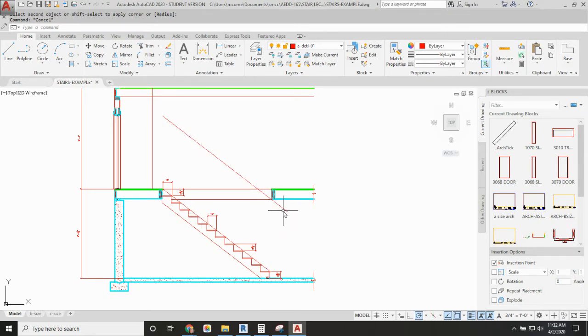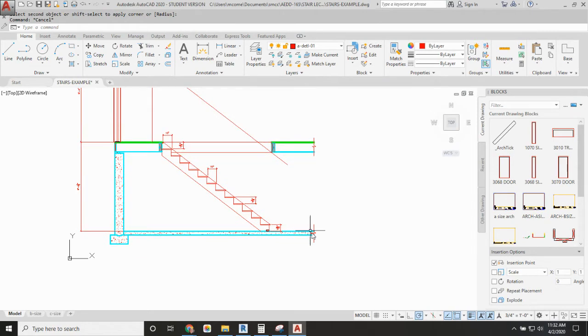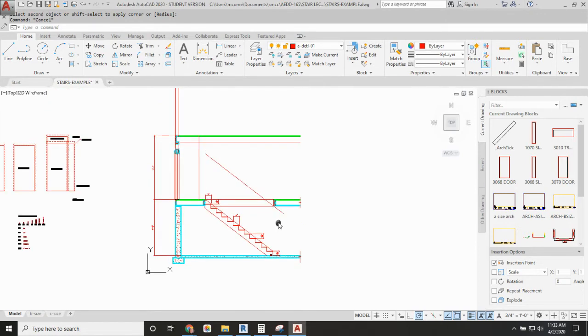And this headroom determines how wide this opening has to be for the stairs. So if I had a lot longer set of stairs, I would only need to provide the headroom space over that first 12 treads. So if I had like 16 to 18 treads here, I only need to expose or provide the opening over the last 12. And I know then that I still will have my headroom. That's basically what you can take away from this.